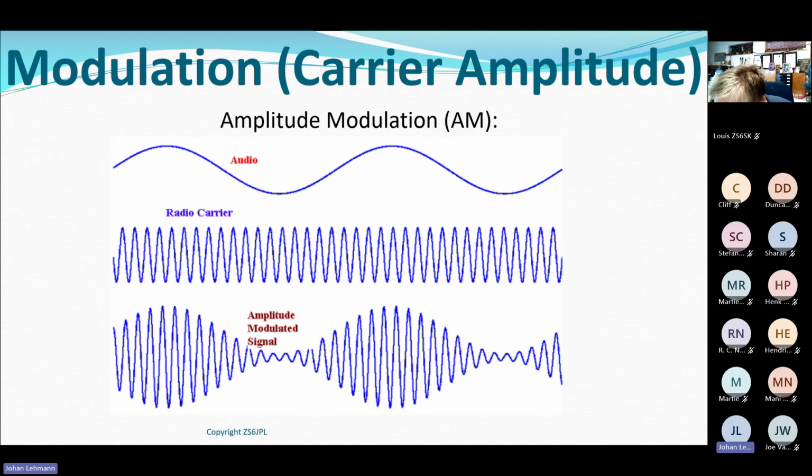If we listen to normal broadcast stations on shortwave, medium wave that use amplitude modulation, they typically run with a modulation index of 85 to 95%. So what does that mean? That won't be a straight line here in the middle. There will still be carrier present.